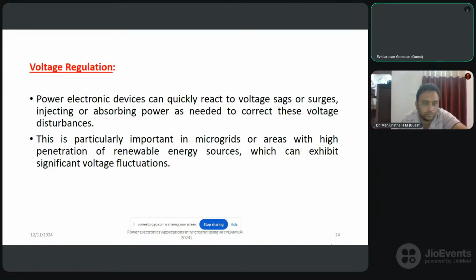they will be increasing the steam input. If they increase the steam input, it has to go and hit the turbine. The turbine moment of inertia has to be overcome. And then the turbine has to rotate fast to overcome the reduction in the frequency. See how much time it will take. It is all mechanical. Hydraulics, right? Hydro systems, mechanical thing, which were happening previously.